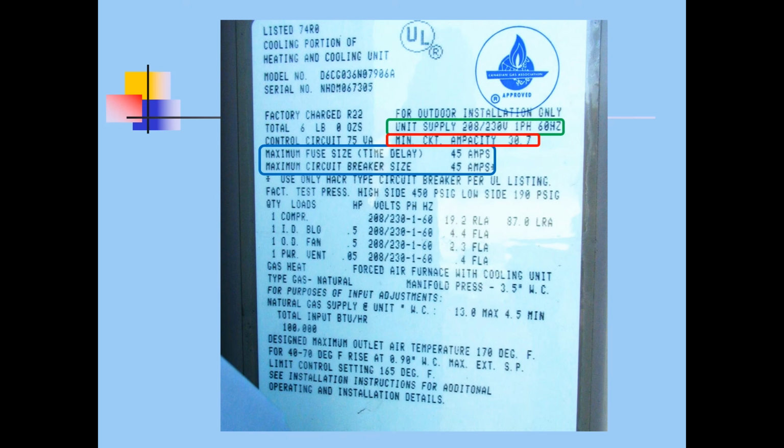The manufacturer has already taken into account all the different rules that we have with motors in section 28, so the things that we talked about when we talked about the individual air conditioning systems in the previous modules, we don't need to apply to. All we need to do is follow the information on the nameplate in order to correctly wire this unit.